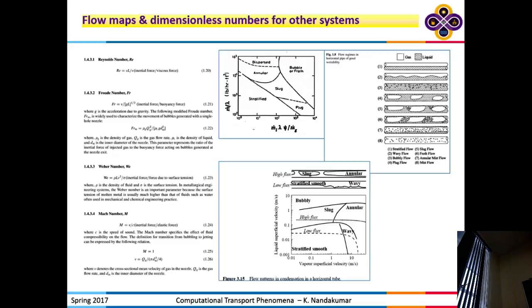Okay, and if you measure this in a 3-inch pipe diameter to measure the pressure drop, that's what, as an engineer, we are interested in, flow rate versus pressure drop relationship. You cannot use that map to design a 36-inch pipe diameter because the flow patterns will change, the boundaries will move around. Right? The same thing happens with a vertical flow, a flow in a vertical pipe.